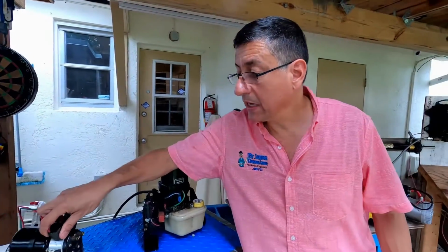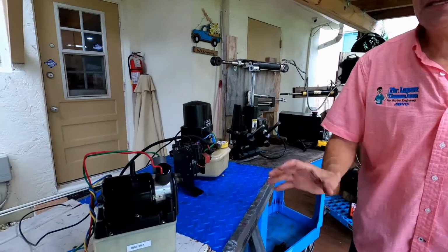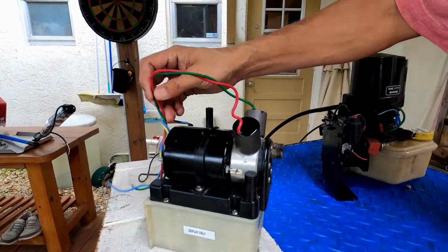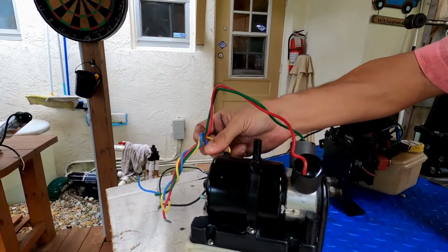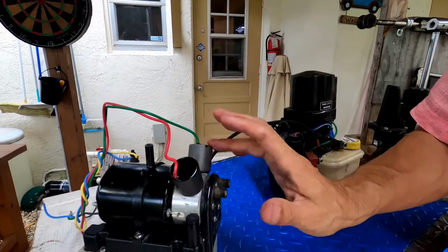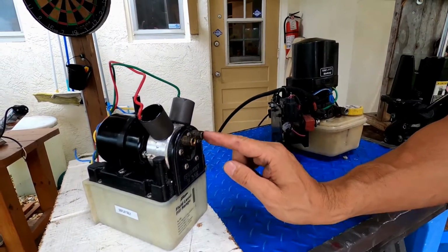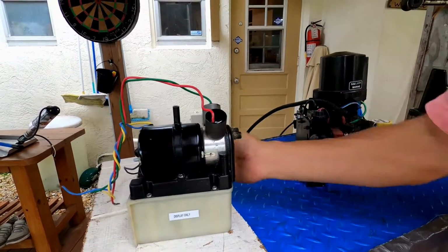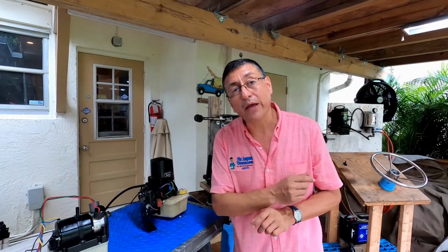Another great example is the trims. This is the pump for the trim tabs. We have a DC reversible motor, the yellow and the blue one, and we have the solenoids, the reservoir, and the ports. This is another great example of a micro central hydraulic unit. This system operates in this simple way.